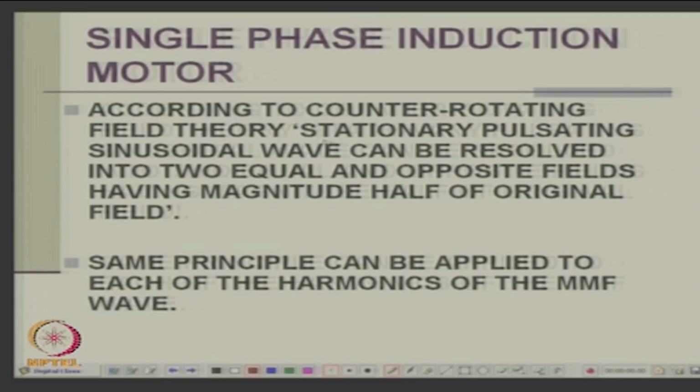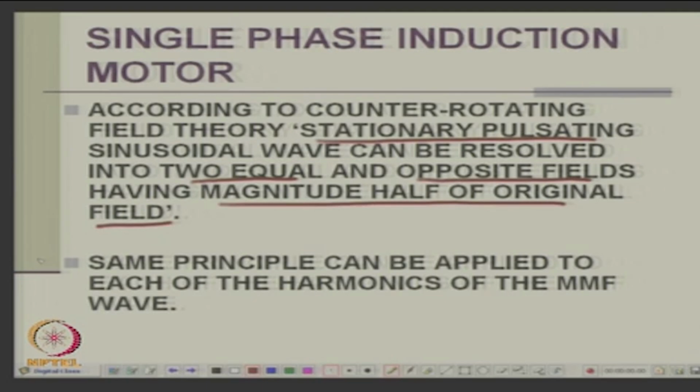Now, we also know the stationary pulsating field is resolved into 2 equal and opposite fields having magnitude half of the original field. I mean this is MMF resolution, not the field resolution, not the flux. We have explained it coincidentally. So, the same principle can be applied to each of the harmonics of the MMF wave.